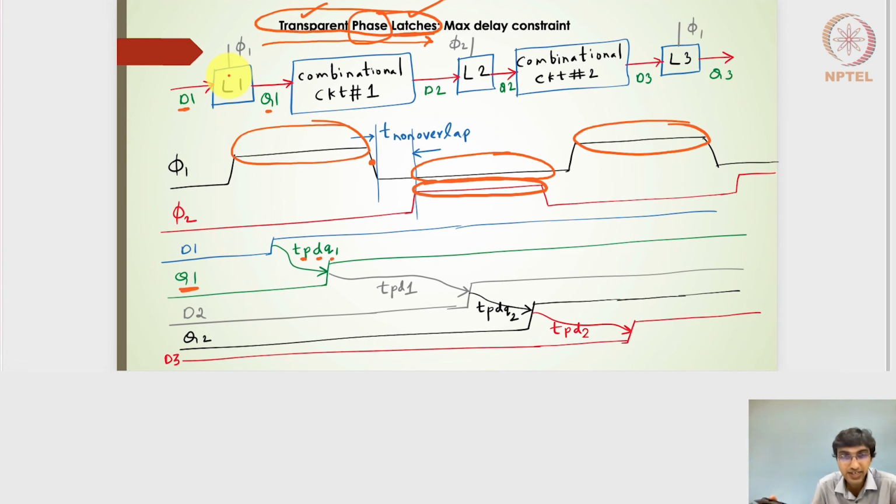In the flip-flop designs, the D used to be ready before the clock edge going high, and then the output was determined whenever the clock did the rising edge transition. And that's why the output is with respect to the clock going high. Here, because the clock is already available, whenever the D comes, the output Q1 will go high, and that's why we say that it is with respect to the D signal, and not with respect to the clock signal, right?